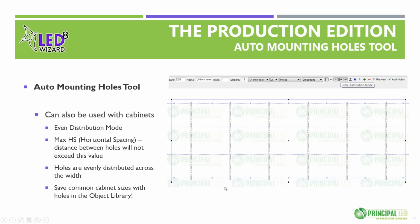So if you have a cabinet or a really big letter, like a Z, for example, and you need to put more than 3 holes, 1, 2, or 3 holes is really the default. But if you want to add more holes, you turn on this tool, and it will evenly space the holes, not to exceed, in this case, 18 inches, right? It may be 16 inches, but it won't be more than 18 inches. So this is a good tool for cabinets as well.